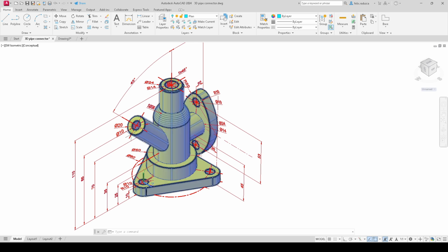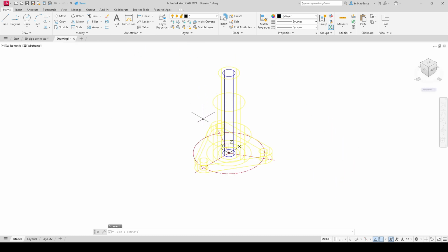These are of a diameter 10 and 20, and they have an axis line that starts from 35 millimeters and is tilted at 45 degrees. So we'll go here to our document, and in order to do that we have to change the position of the coordinate system to make it easy for us to draw those axis lines. So we'll type in the UCS command and we'll say that we want to move it to a certain point, 0, 0, 35.